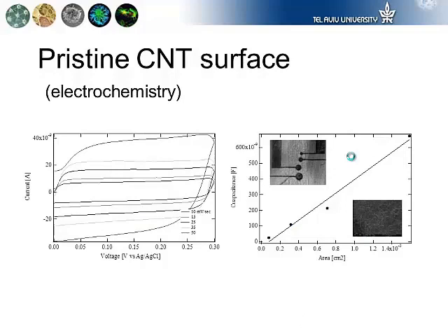And of course, the electrochemistry is a very important feature. It's probably the most important feature. And again, we get very similar results to what I've shown you on the silicon substrate. So this is, again, cyclic voltammetry. This is current as a function of voltage in a 3-cell setup in PBS using electrodes of different sizes. And you can, again, systematically measure the capacitance, and from that derive the specific capacitance, and you can really confirm that you have a very high density, high surface area capacitive electrode.